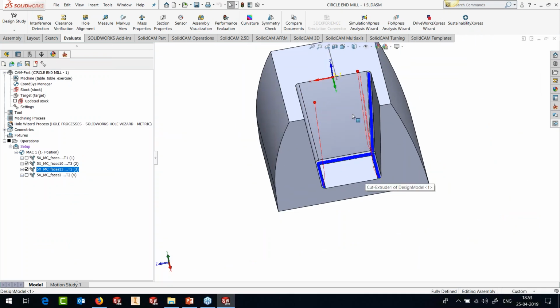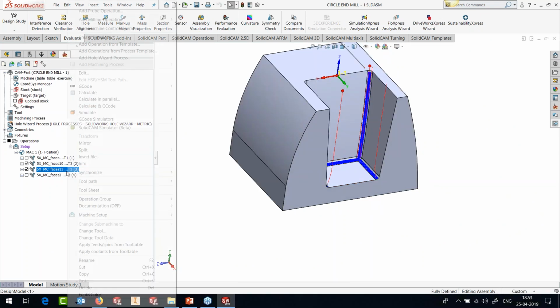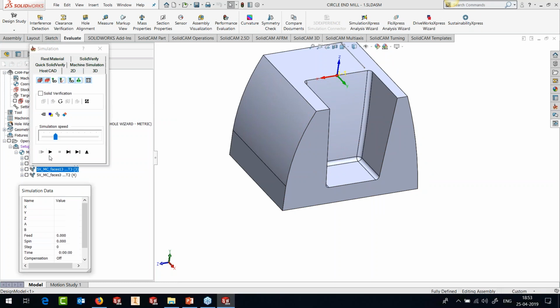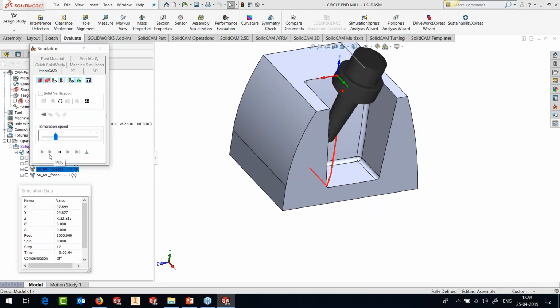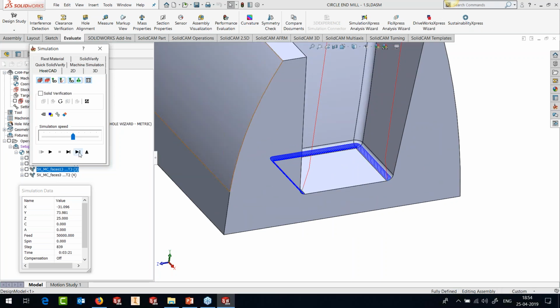Okay, so in the same way, I have machined the bottom fillet. What I've done is I've defined one point out here, and I've used this point as a point for my tilting. Again, with the same tool, you can see that again I'm working with the tip of the tool. And we finish the fillet.